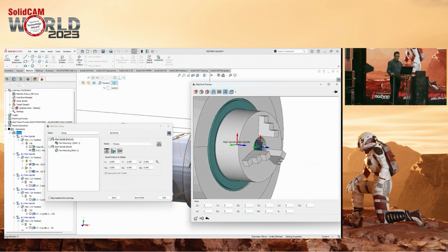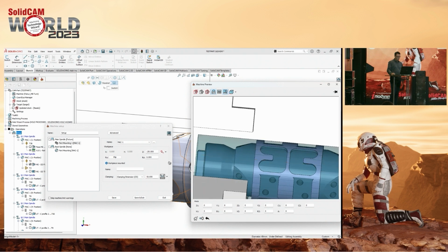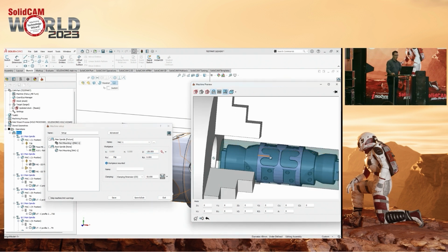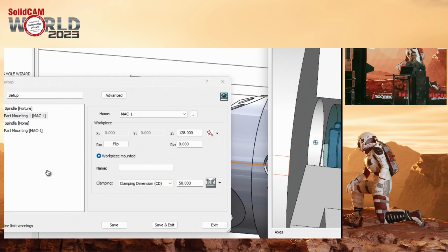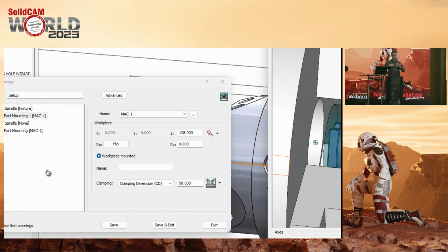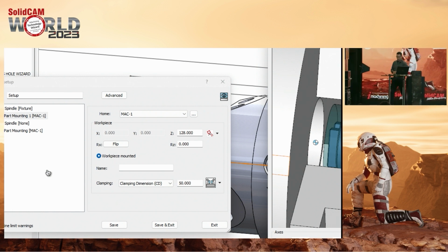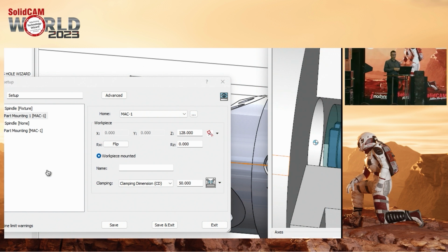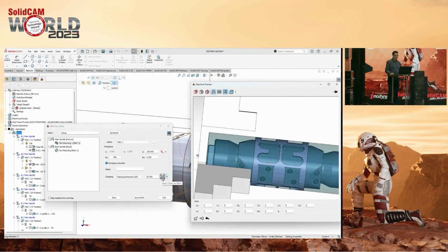Okay? I'm going to open my preview. My part is over here. I'm going to move it to the part page. Let's say I want it here. Okay, what we have here, more. It's obvious that my chuck is moving everything. I can control the clamping positions and so on. I have here a clamping axis that I can control. This 50 that I put, you can see it also here. But we have something new. We have also something we call the auto clamp option. So I'm going to position it here, and I'm going to click on this auto clamp on stock.